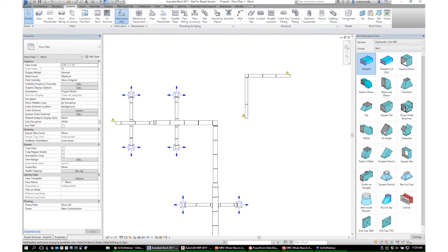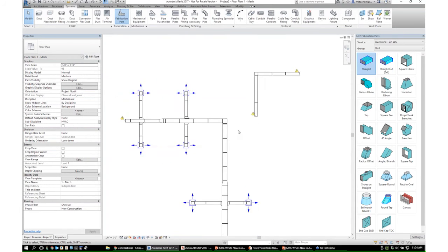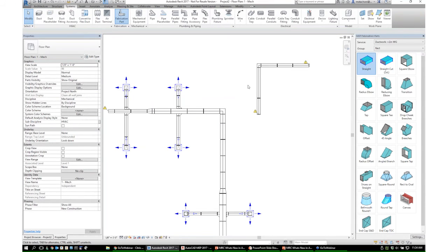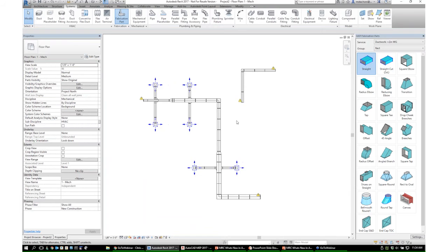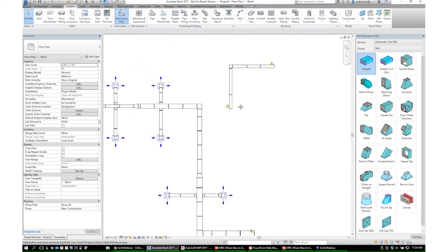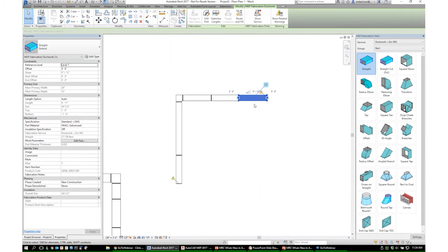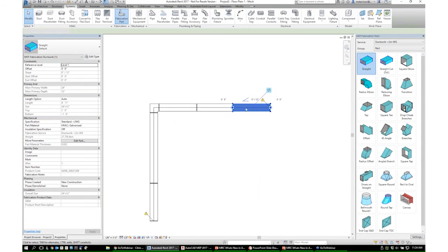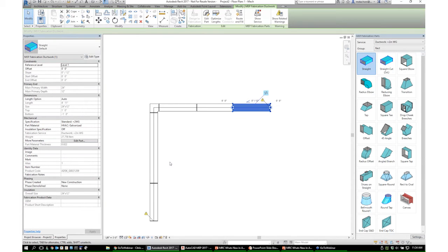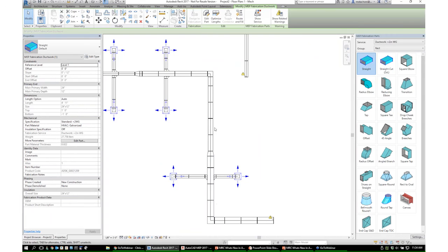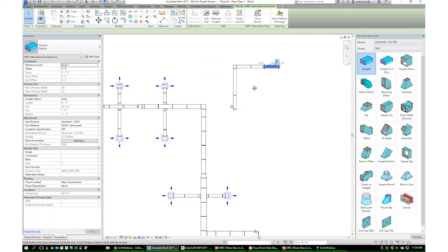Now when you're laying out fabrication parts, you have to understand that it is markedly different from laying out regular ductwork in Revit, because you saw before that I was able to break this ductwork right here, and it automatically put this transition in here and here and here. Fab MEP, or the fabrication parts facility, doesn't really do that. If I look at this part right here, it's driven by the design. So I should be taking an MEP duct system and converting it into parts.